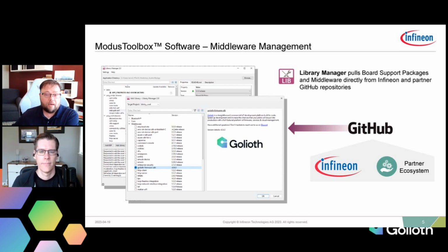Or I'm targeting my actual hardware, right? Because we're going to go to market on real hardware. So I'm able to manage that BSP and plug and play, pull out the BSP for the development kit and plug in a BSP for my hardware, and be able to port that application over quite easily.